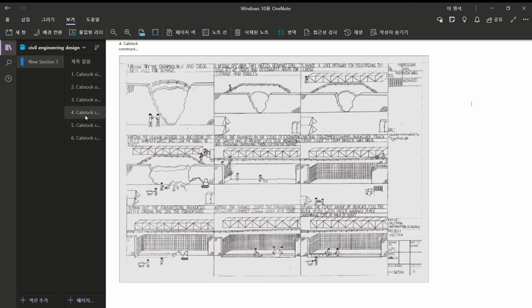For step 4, the digger with a replaceable jackhammer will be brought on site. We decided on the digger because it is small and it'll be able to fit through the narrow road behind the failed retaining wall to get down to the construction area. It will be used to break off excess part of the damaged wall. The workers will clear the rubble using shovels and wheelbarrows and store the material so that it can be reused.